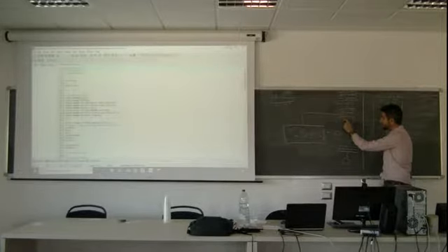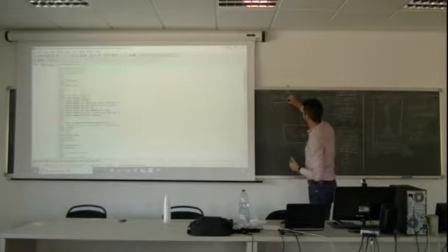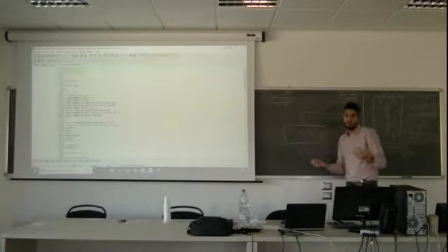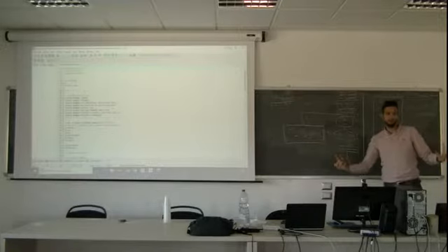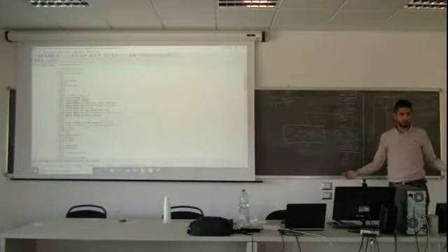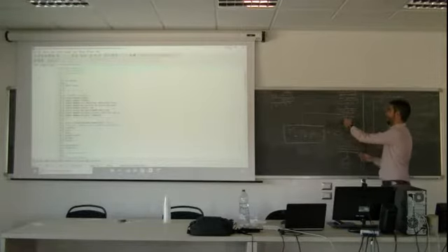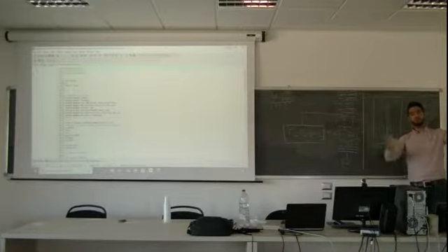Remember that inside the equations of the temperatures, there are assumed values. Because when I am calculating this node, I am assuming what is the temperature of here and what is the temperature here. I need to assume. Otherwise, I cannot calculate the value of the node, right? I need to assume what are the temperatures of the neighbors. Otherwise, I'm lost. So, okay, I assume again. I calculate. Again, I have one solution, one assumption.